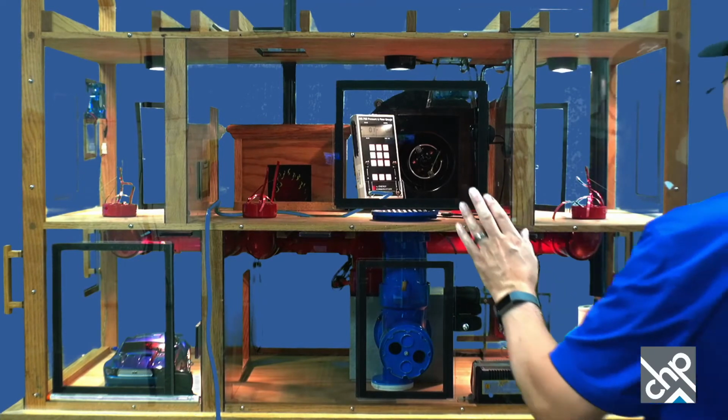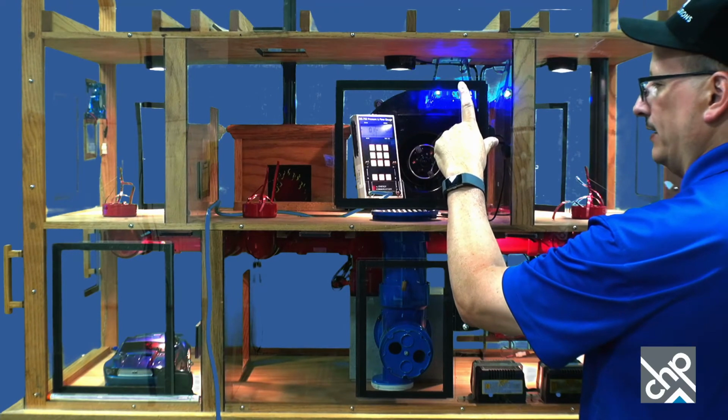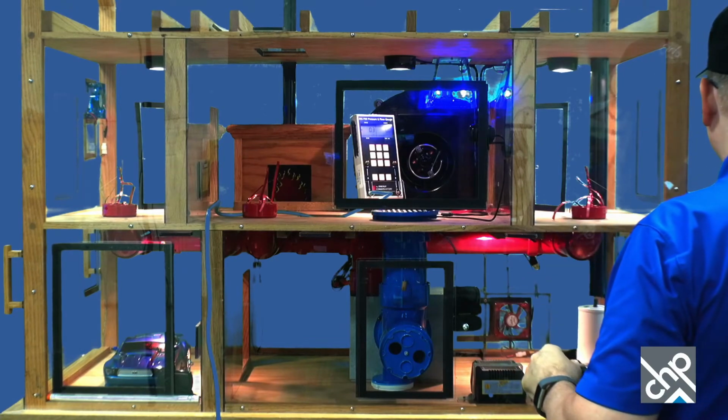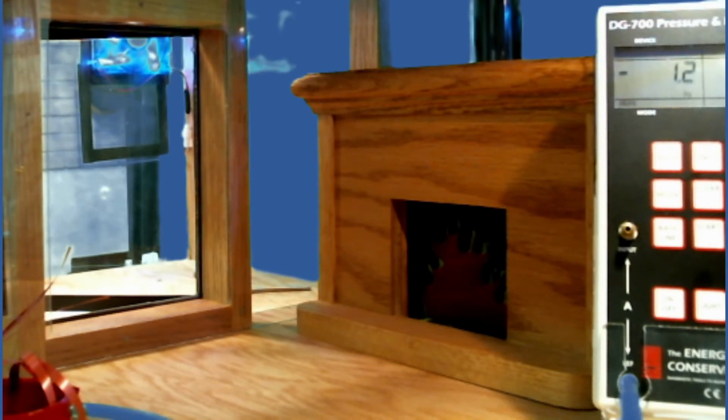So we're going to turn on the kitchen exhaust first, which is going to be up here. You see that come on, and we're at negative 0.3 in there. Let's see if I can get close to it. So you can see it there, negative 0.3. Now the bathroom fan, you can actually see that in this picture, over there to the far left. I'll turn it on. You can see if we get any pressure change from that. So there's the bathroom fan.